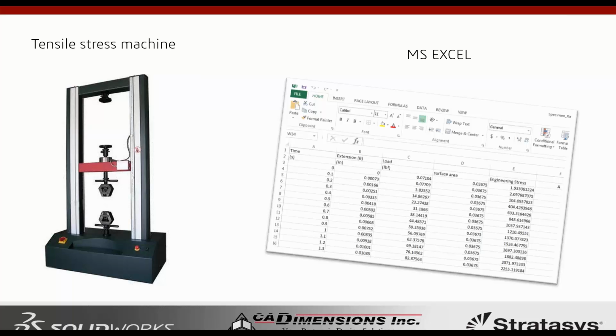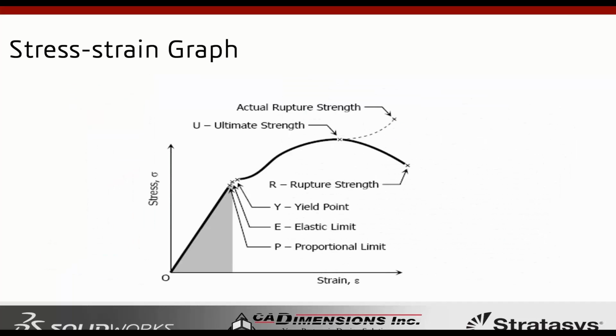Well, I'm going to go through an example today where I do both, and we can see that when we run SolidWorks simulation analysis simply using hard numbers, so your yield stress, your tensile stress, your elastic modulus, those constant numbers in your analysis, the results you get are much higher than the results you would get if you were to use actual data. All right, so with that said, let's jump right into SolidWorks.